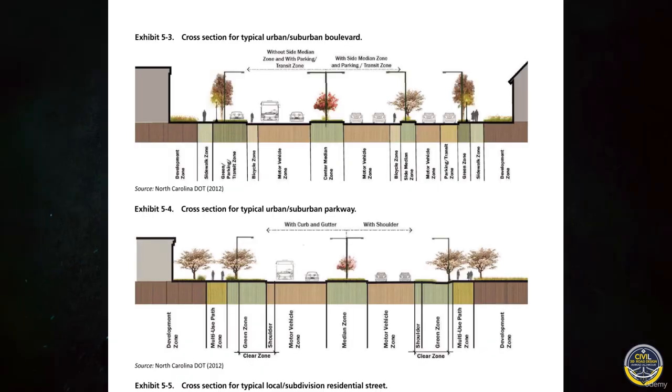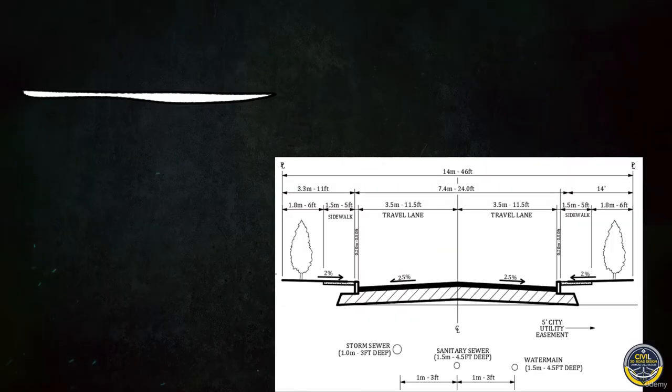In Civil 3D, a corridor is built by sweeping an assembly along an alignment profile. Think of an assembly as the cross-section template of your design. It describes lanes, curbs, shoulders, and side slopes.